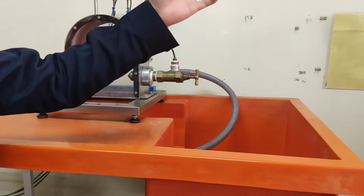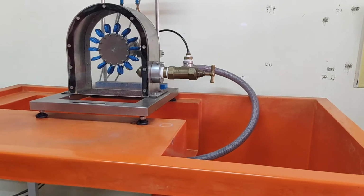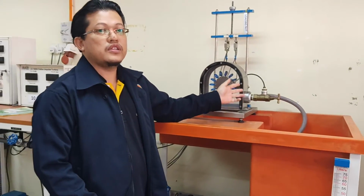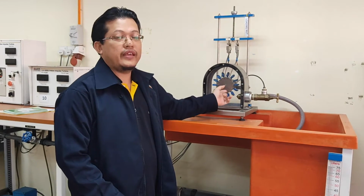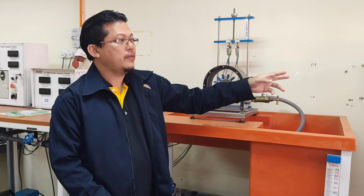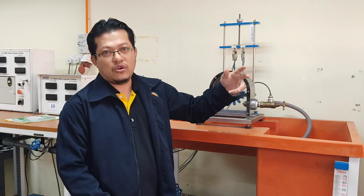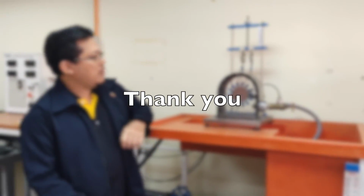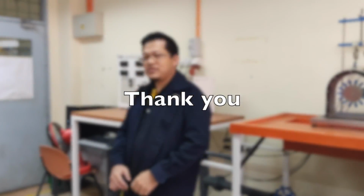So the difference between Francis and Pelton: for the Pelton one we need to convert first the flow energy to kinetic energy. But this one we use both kinetic and flow energy to harvest the energy from the water. Okay, I think that's all from me.